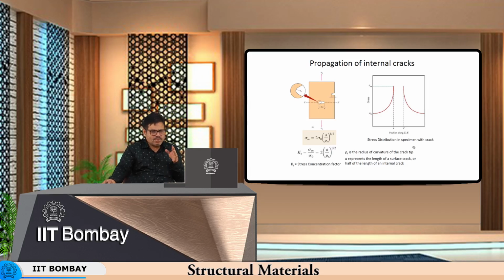So, everything is being shown exaggerated. For example, here the opening is usually not so big, and here also you do not have such a big flaw, but just for the sake of understanding the concept, it has been drawn that way. So, we need a factor like the stress concentration factor, Kt, which will measure the intensification of stress at a flaw.